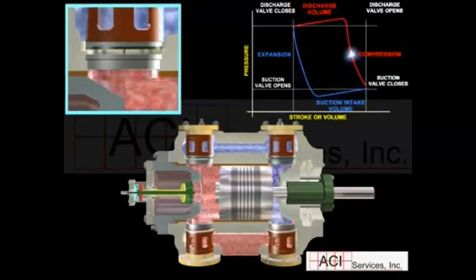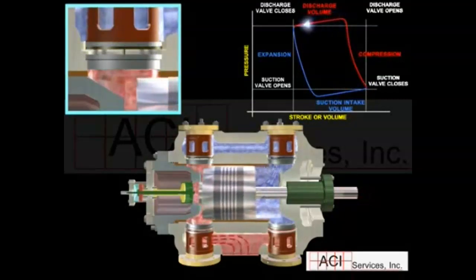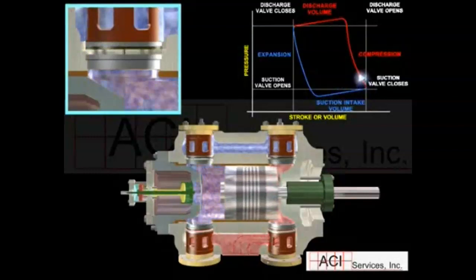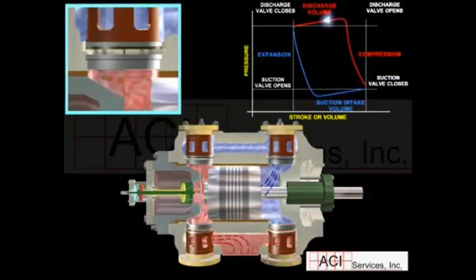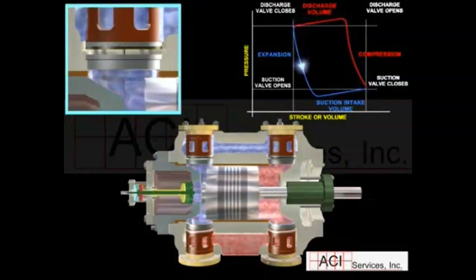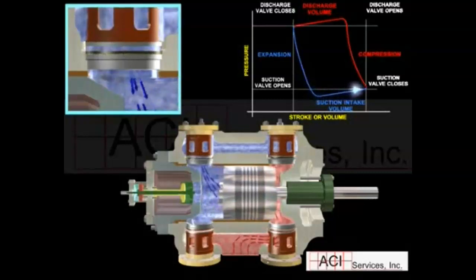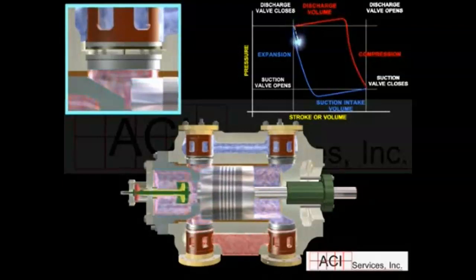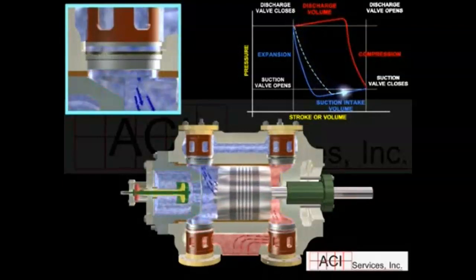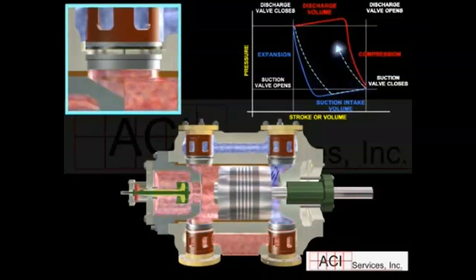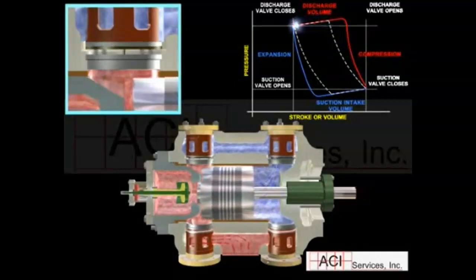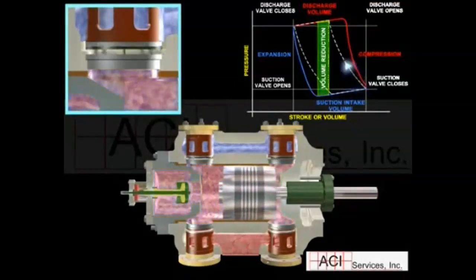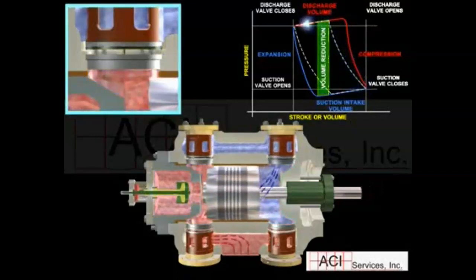When it's pulling in cool air, whenever it's compressing, it's pushing out warmer air. Why? Because you have forced those molecules together, and what happens when you force them together? You create heat and friction. But you're getting compression on both ends of this. Okay? This is why this is known as a double acting compressor or compression.